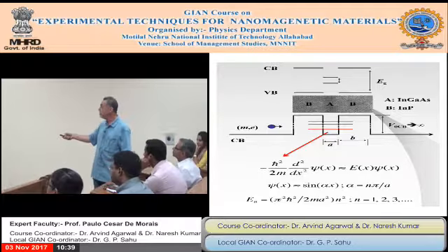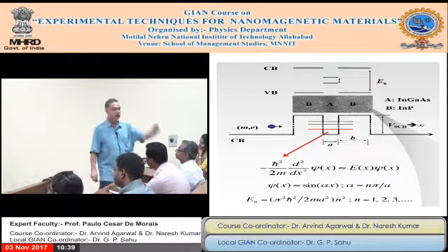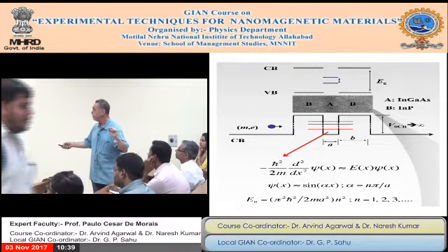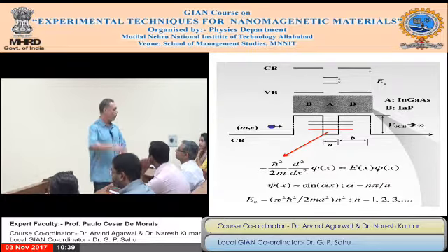And you can see here, you have one phase A, one phase B, and another phase B. The phase A was a thin layer of indium gallium arsenide, narrow band gap. And the barriers, which we call B, are indium phosphide, wider band gap.